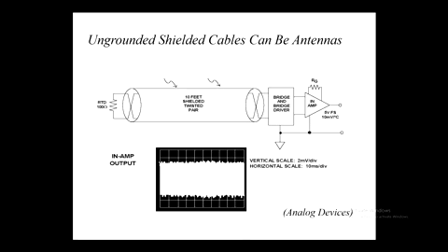You have to be careful with grounding, because suppose you put a shield in and you don't use it properly, then you've got a piece of wire ready to accept interference, and it will act as an antenna then. It picks up the interference and passes it into the signal lines if you don't have it grounded.